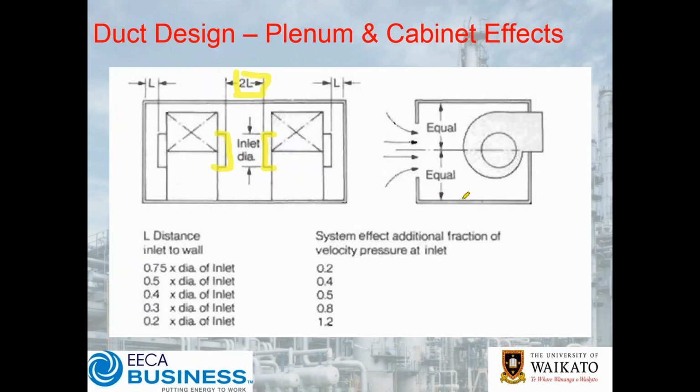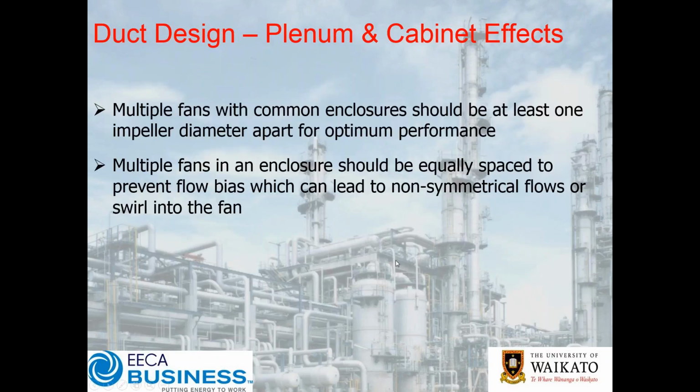Any less than that, and the two inlets are going to start fighting each other. And as you reduce that distance, the effect in terms of pressure reduction and all the rest of it gets more and more pronounced. So it's just really important. It really is common sense, but it's amazing how uncommon common sense can be.